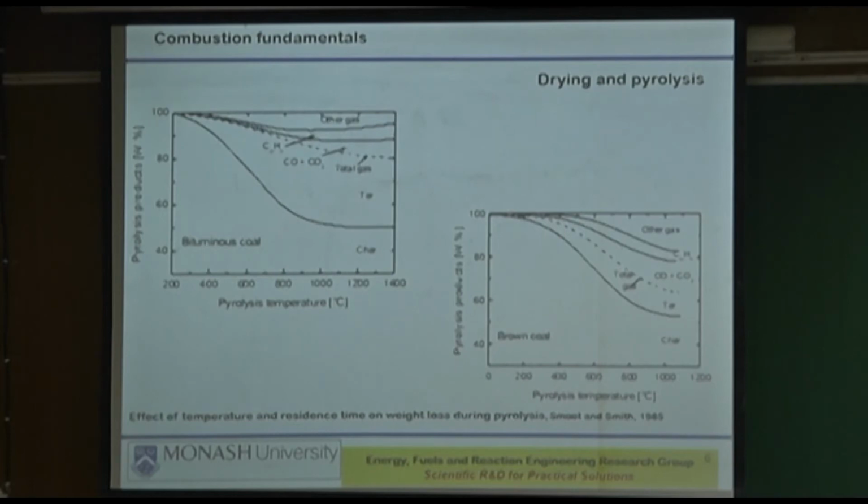If we get any significant amount of tar near the vicinity of the burner, because that's where the pyrolysis takes place, then you will have to have ways to break the tar down, and the way to break the tar down is to inject more air through the swirl so that it quickly breaks the long chain hydrocarbons into smaller chains. That's how it is done.